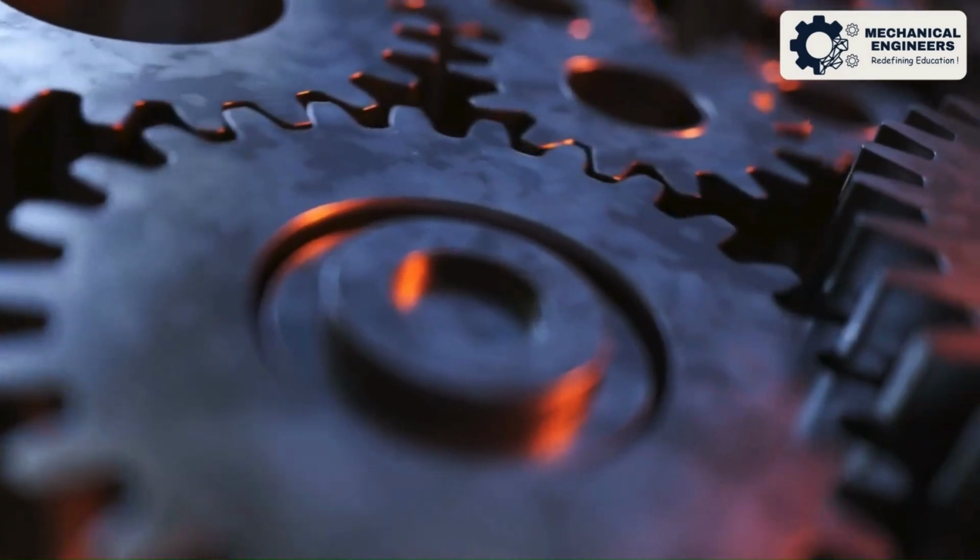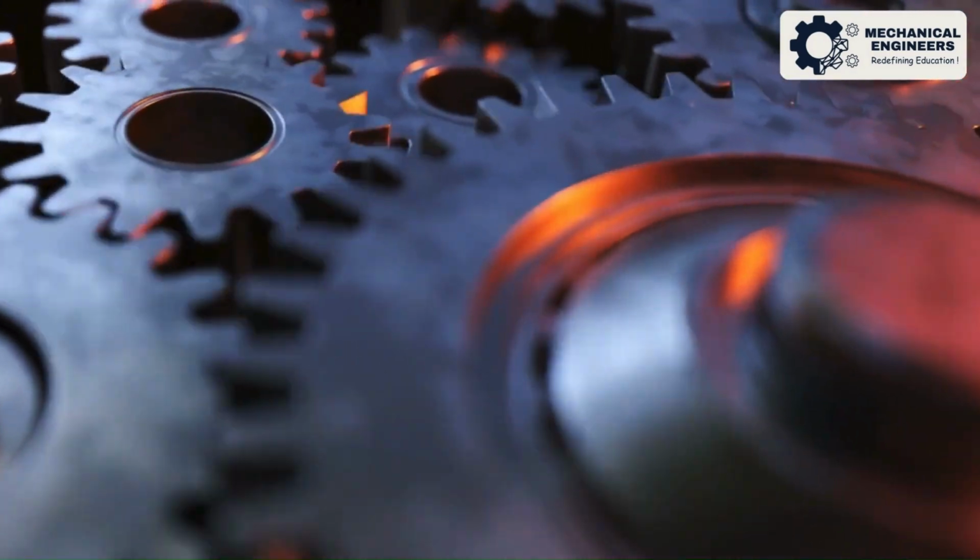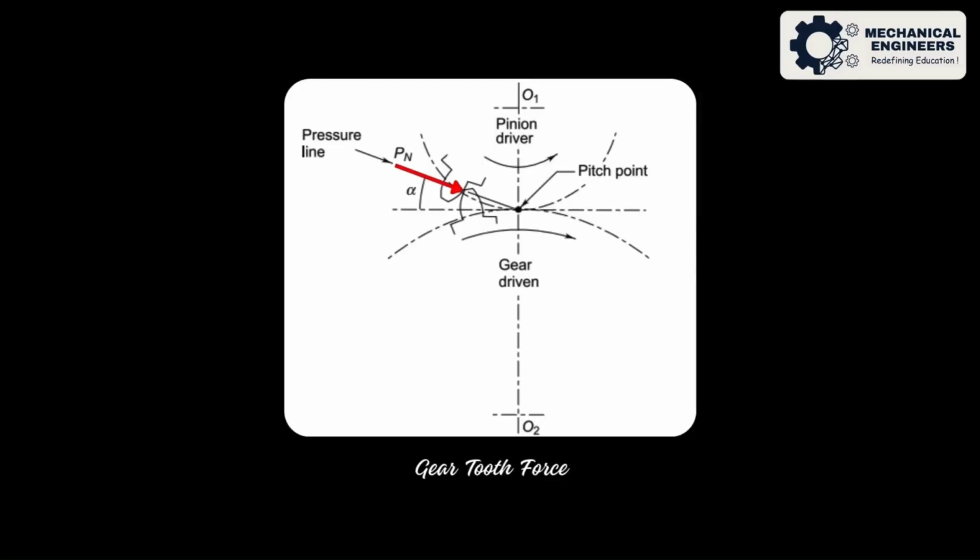In gears, power transmission hinges on the interaction between the driving and driven gears. Picture this. The tooth of the driving pinion exerts a force, known as Pn, on the meshing tooth of the driven gear. This force follows the pressure line, a fundamental principle in gearing.